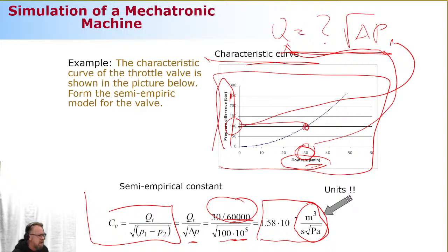And of course, you can kind of play with any units you want, but here's another important lesson when you're modeling hydraulics. Stay with the SI units. And don't convert them to millimeters, but stay with meters, even though sometimes you end up with very small or big numbers, but it really helps you a lot because conversion from these units to something else is possible, but again, you need to be consistent.